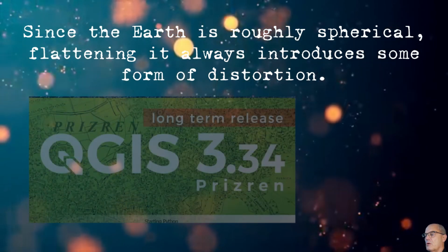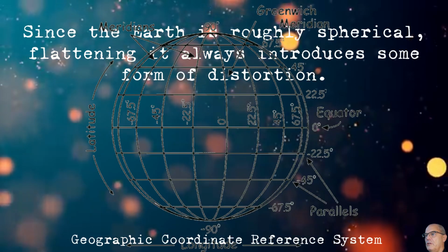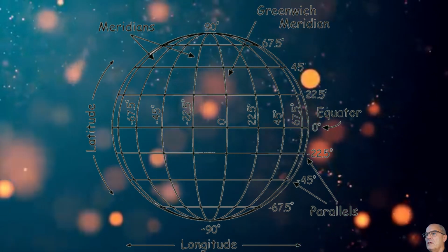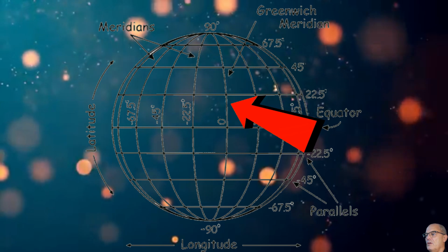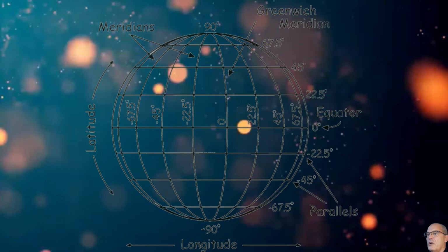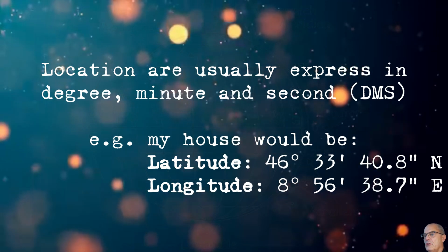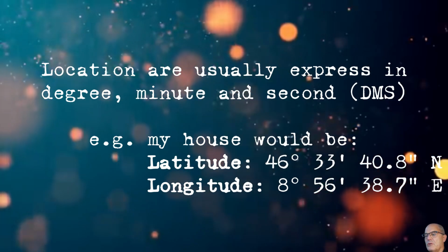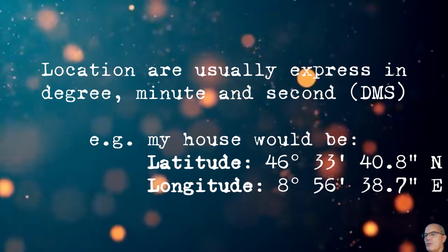By default, our software or our GPS has a geographic coordinate reference system displayed in latitude and longitude, where we know that the latitude is on the equator with 0 degrees and the longitude is the prime meridian going to Greenwich, London. So by default, this geographic coordinate reference system shows coordinates in degrees, minutes and seconds, which makes it rather complicated for the computer to make calculations like identifying distances, surfaces and volume.